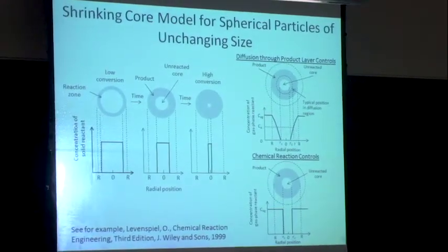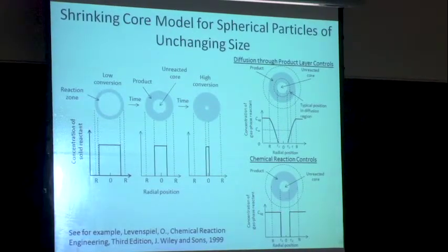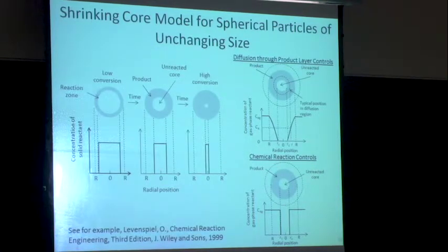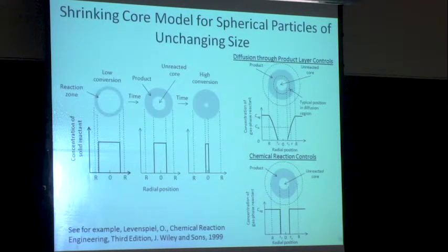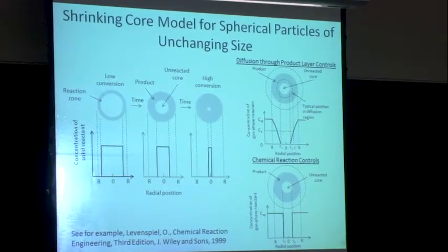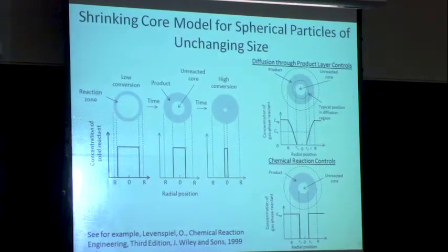What happens also as the particles get smaller, as I mentioned, if you're at low pressure and the temperature of the particles is very close to the surrounding temperatures, and that means I'm below the vaporization temperature of aluminum, then the nanoparticles are going to burn not in the vapor phase, but more like a shrinking core model. And what this means is I'm not going to be able to vaporize the metal oxide on the surface. I'm not going to be able to vaporize the aluminum. And so the question is, how does the nanoparticle oxidize?